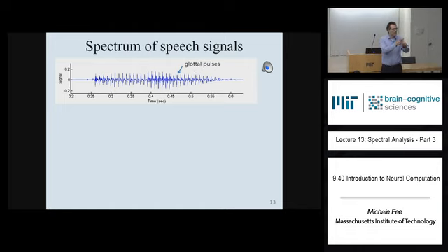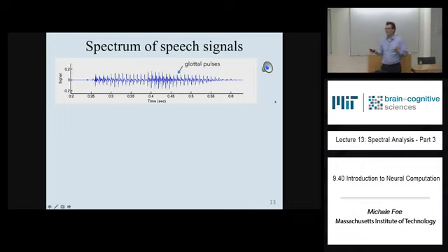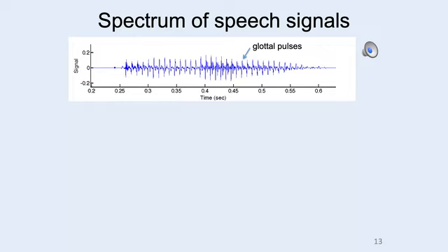What would a signal look like that just has a peak at 100 hertz? Has one peak at 100 hertz. Or let's say the Fourier transform would have a peak at 100 and at minus 100. That's just a cosine. That's not a train of pulses. What's the Fourier transform of a train of pulses? Those of you who are concentrating on this right now are going to be really glad on the midterm. What's the Fourier transform of a train of pulses?